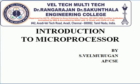First one is the general purpose processor, where the instruction set is not designed for a particular application. For example, the 8085 microprocessor and the 8086 microprocessor. What is the main difference between 8085 and 8086? The 8085 microprocessor is an 8-bit microprocessor, so 8-bit data is executed at a time. And the 8086 microprocessor is a 16-bit microprocessor, so at a time it can execute instructions in 16 bits.